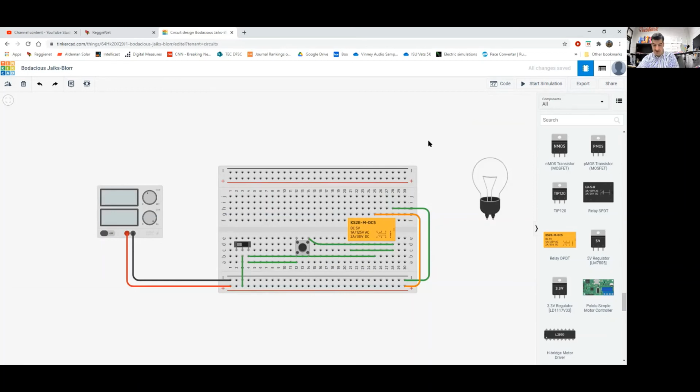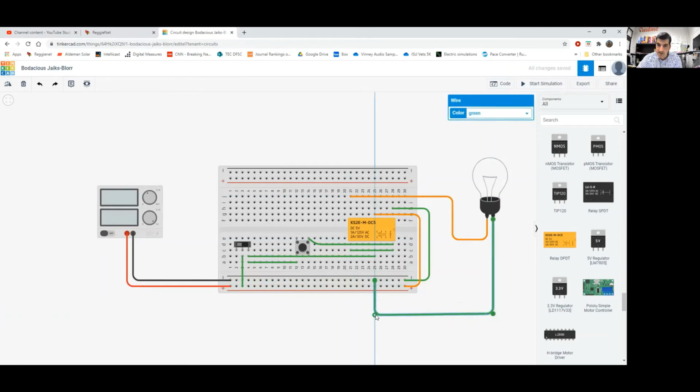Now the second wire of the second rung goes from the normally open contact associated with that common. So I got to go from any of these connections to the output, the light bulb. So I'll go from right here, and then I'll go over here, and then down there. Okay, and I got to make it orange because it's part of the second rung. And then the very last one, oh, that's easy. It's just the output of the light bulb to ground. So I'm going to come down here, and I'm going to be going to anywhere in the ground rail. All right. Oh, got to make it orange.